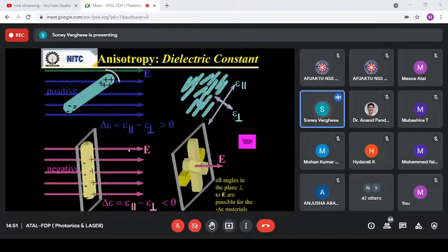So that is the reason why the material will twist when you apply an electric field, because the electric field interacts with this polarization of the molecule, then the molecule starts rotating. So that is the basic idea. The molecule should be polar, then only it will be twisted by the electric field when you apply it. Then the wave guiding will be lost, and the light will pass. So the polarization is very important.